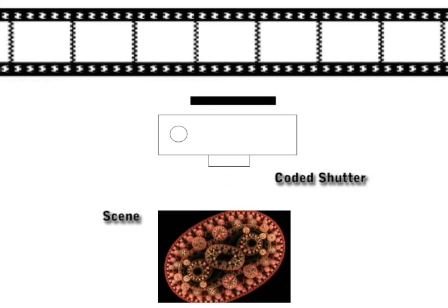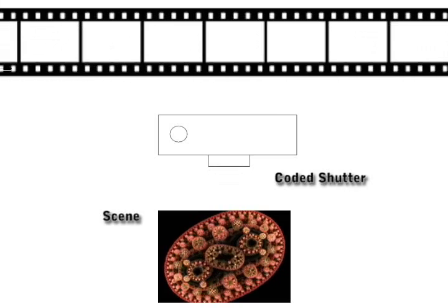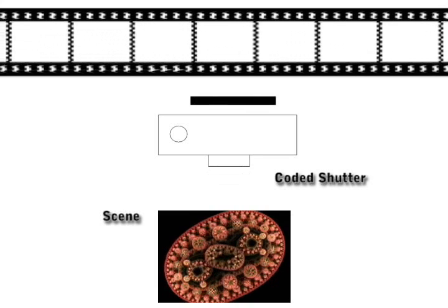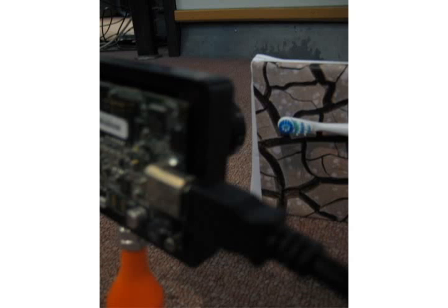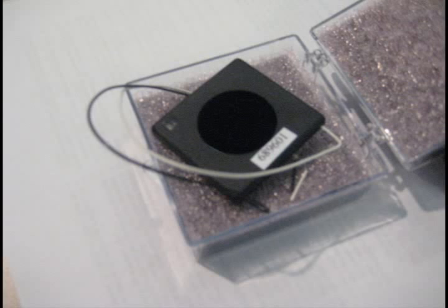Our system records linear combinations of radiance values by opening and closing the shutter during exposure. It can be implemented directly using the commercially available Point Grey Dragonfly 2 camera. Even finer temporal resolution for the coded strobing shutter can be achieved using a DisplayTech ferroelectric shutter.